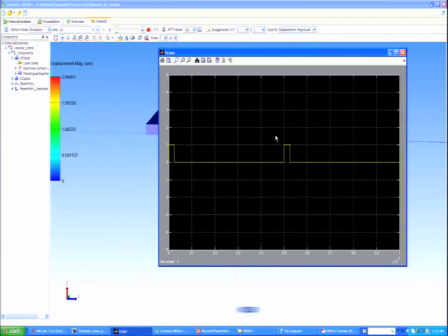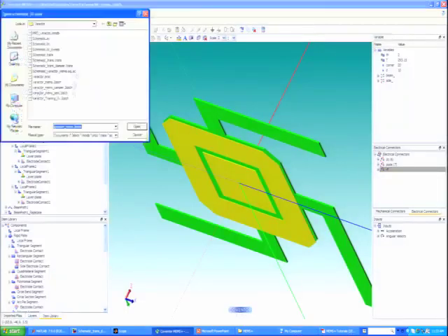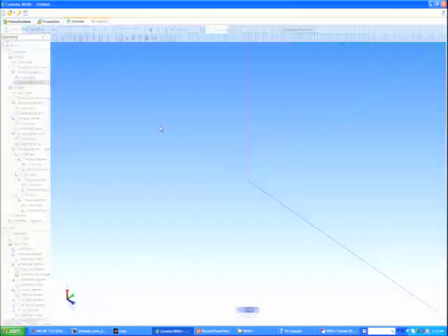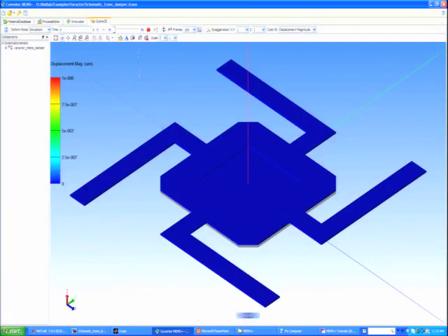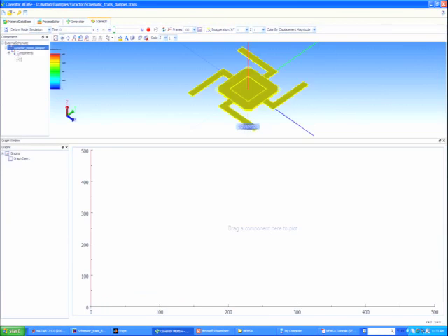As usual, I'm not going to look at this in MATLAB. I prefer the plotting in MEMS Plus. So I close this. I close the DC sweep. I go to this, and I say details, and the result is .trans for transient. I open it, and I do the same thing as before. I plot the center of the plate.